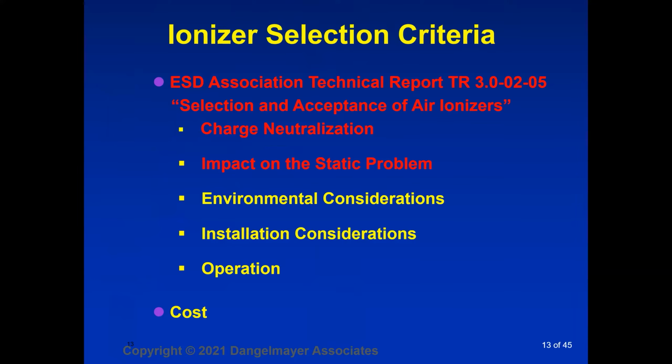So the first two issues that it talks about is, of course, number one, charge neutralization. How well does the ionizer neutralize static charge? And the second thing it covers, and this is very unique in terms of standards documents, is it tells you that if you're going to use an ionizer, you should test for the impact on the static problem. Very interesting.